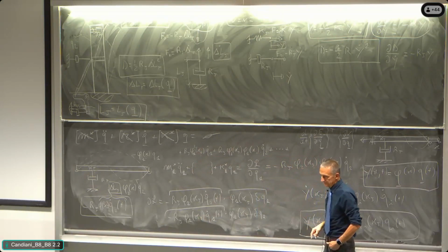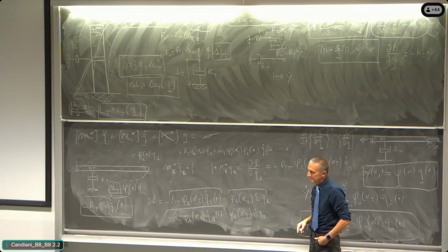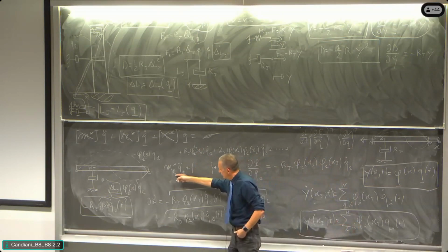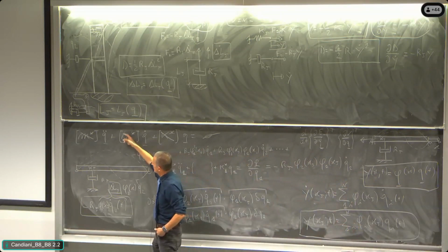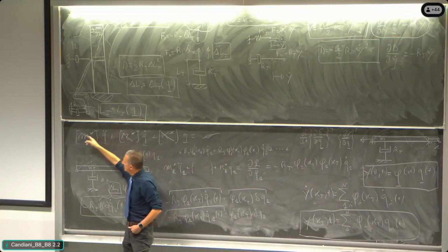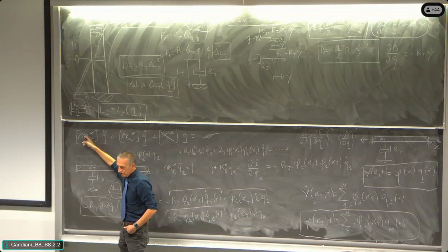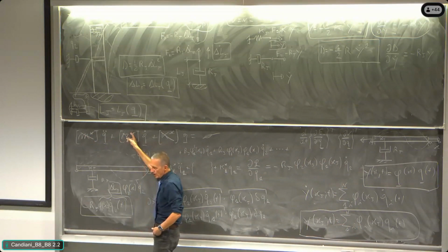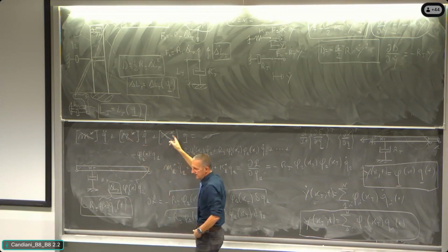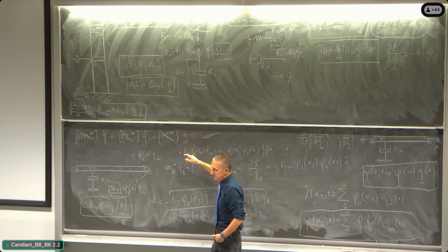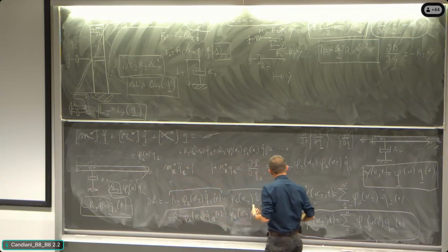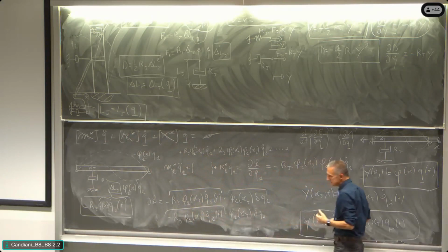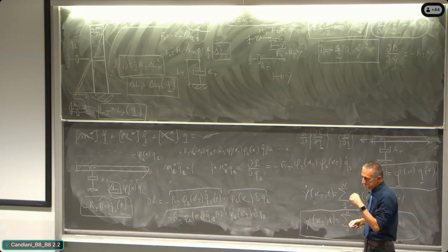the coupling term. What does it mean, coupling? It means that into the equation here, where I was supposing to have just the coordinate Q1, M1 star Q1 two dots, R star 1 Q1 dot, K1 star Q1, in my idea, in principal coordinates everything is diagonal.